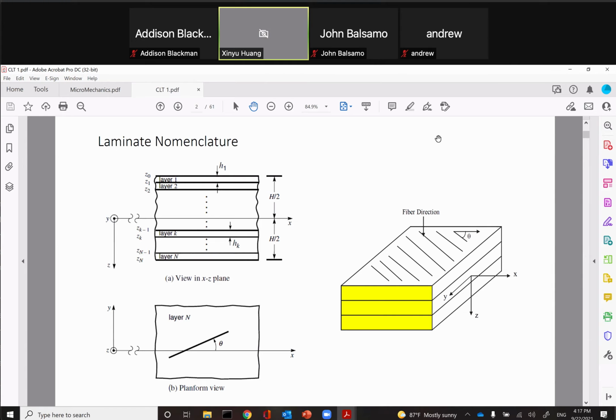All right. So let's introduce some nomenclature. The plate, since it's made of multiple layers, we have to have a way to communicate the structure so that there's less confusion. So typically you put a coordinate system together. You can use XY to describe the in-plane, the midplane. You find a geometric center of the plane, the top plane, bottom plane, the center plane. You call it XY. And you have a Z direction. Z direction is perpendicular to the plane.